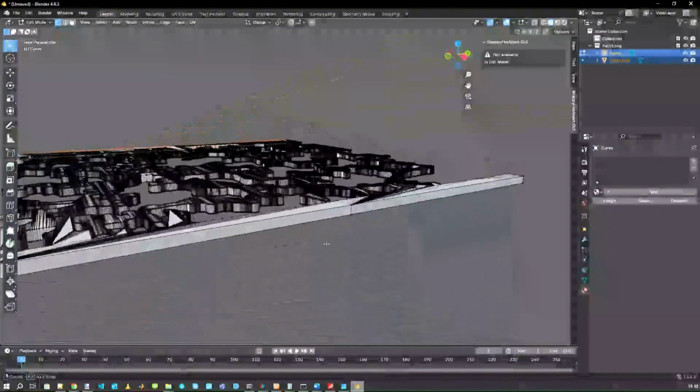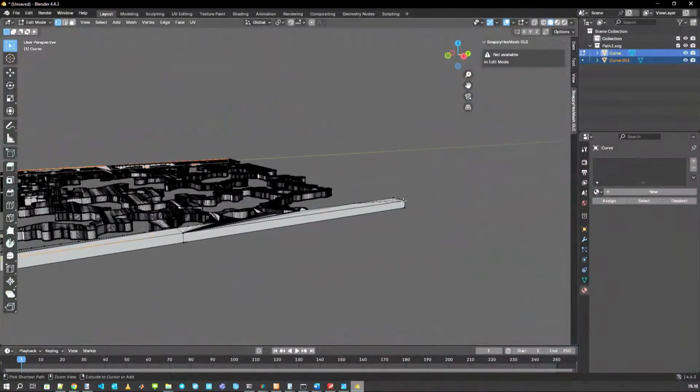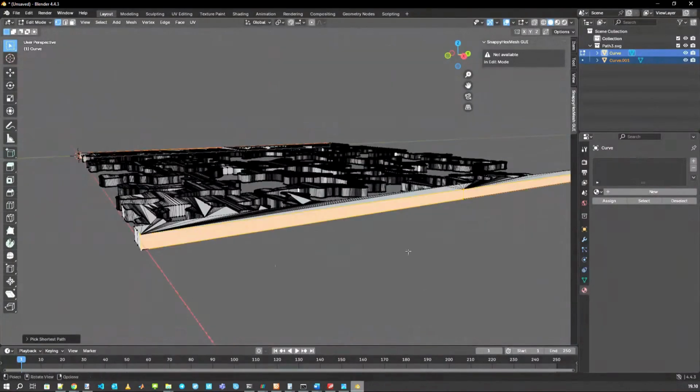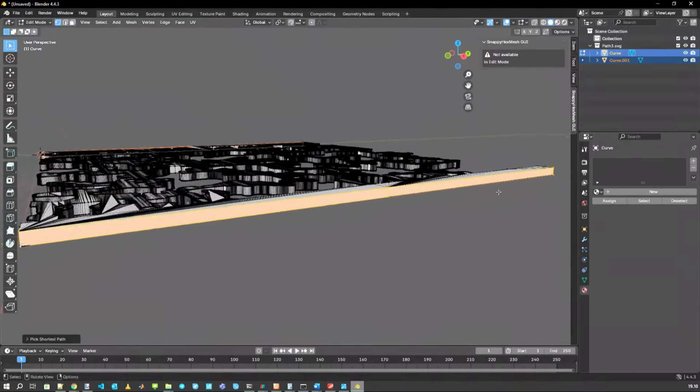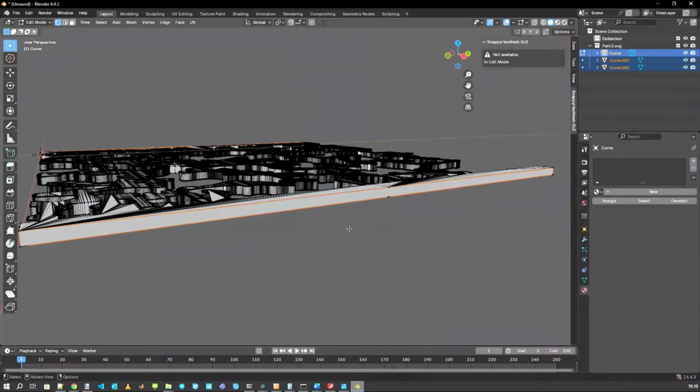Let's turn the geometry to the other side. Again, the first one, the second edge, third edge, and the right edge. So again, we have the face that we want to separate as the outlet of the system. So we press the separate selection again. As you can see, we have two other objects over here.